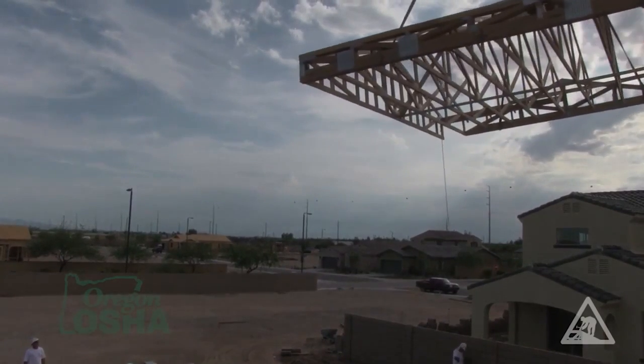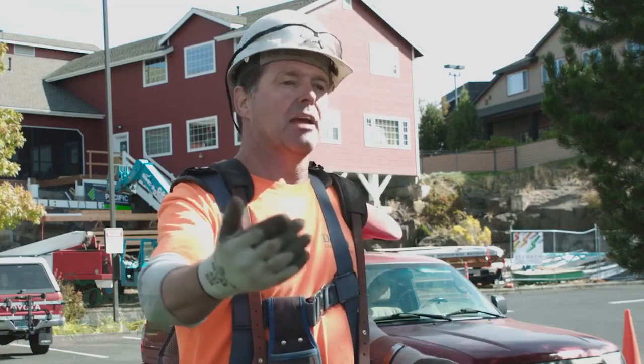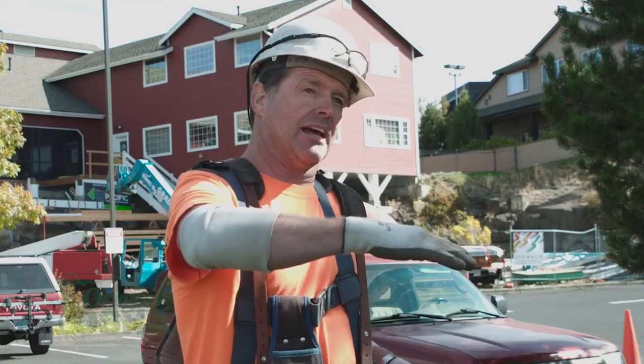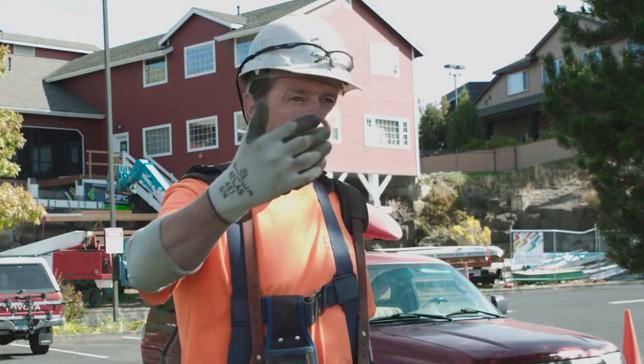Another way of doing it that's more industry standard is that you would, for instance, get your gable truss and sheet it while it's down, and then stand it, brace it, and then roll a couple of trusses.